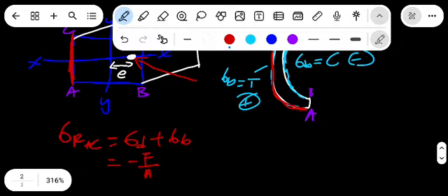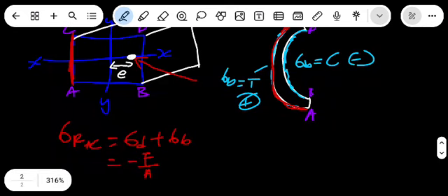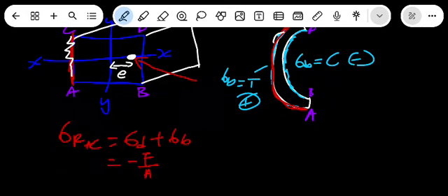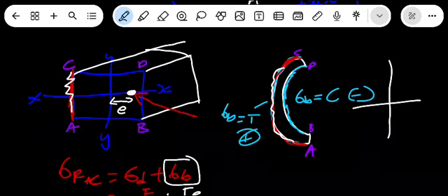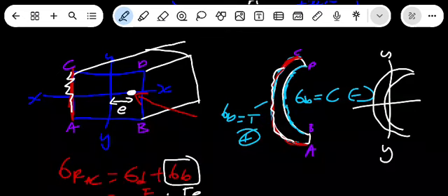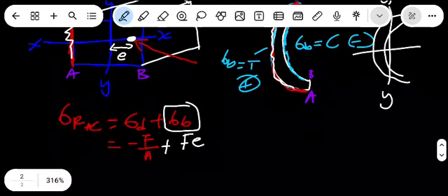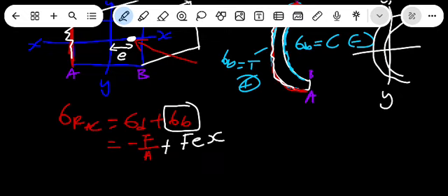But now we are focusing on this side here, where we have tensile. So this will be the bending stress at that side. Since it's tensile, it's positive. But because it's bending along the y-axis, if you have a Cartesian like this, here you'll use x. The centroid now will be x. You no longer use the other one.